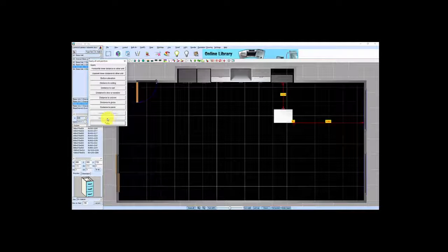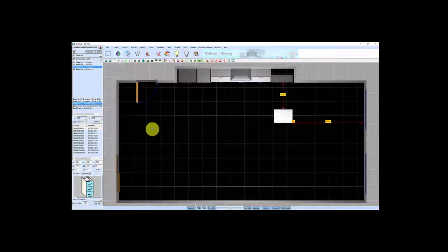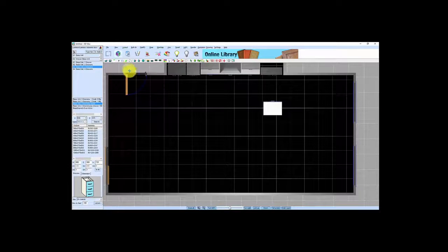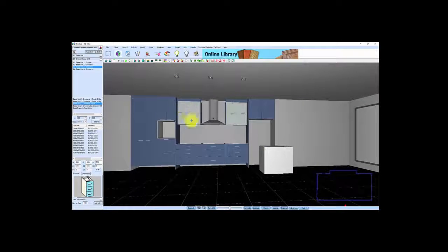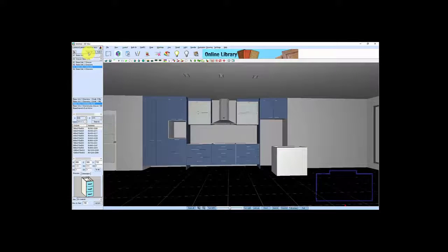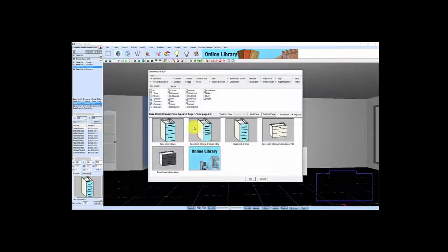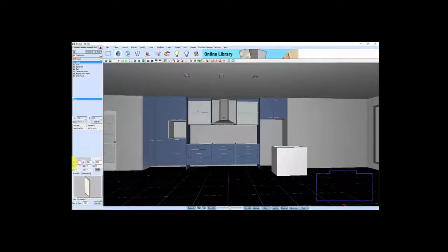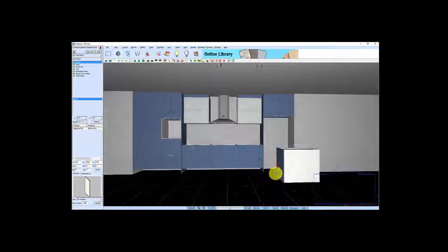What we'll do then is I will then go exit. From there we can now start placing our other cabinets. So what we do is we'll go back to our original view, which is our 3D view. So you press the world over the top there, and what that does, it takes you back to this view here. So from here what I'm going to do is press type select, and I'm going to create a dishwasher space. Decorative panel, go OK, press 16 mil, 580 deep, 720 high. We'll press layout, bring that over and place that onto the cupboard there.